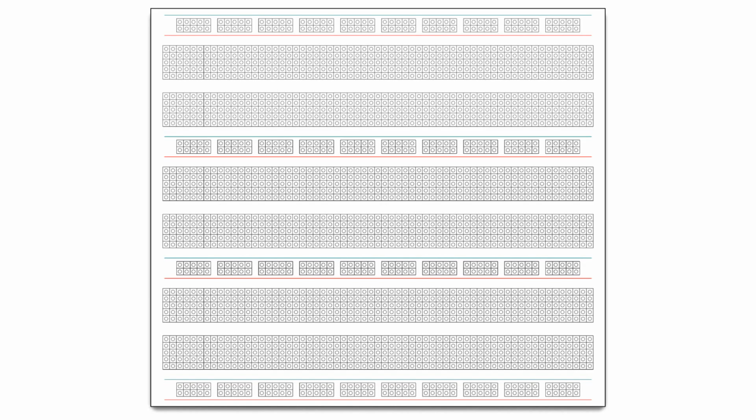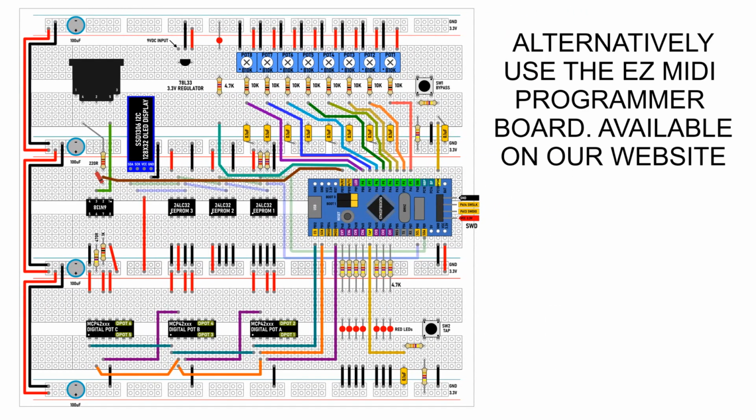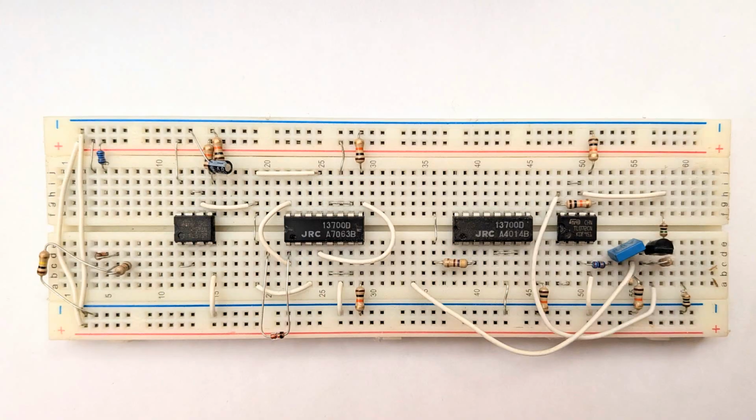To follow this tutorial, we recommend a 3-tier breadboard. This layout gives us space to build the entire EZ MIDI 2 control system. At first glance, this might look complicated, but this setup includes everything, including the EEPROM programming tools and every possible option EZ MIDI 2 offers. You only need to wire up the features you want to use, but with a full setup, you'll be prepared for future designs. You'll also need a separate standard breadboard to build your actual prototype effect. This keeps the brain of the operation separate from the muscle, making debugging and experimenting much easier. It also keeps the different supply voltages separate.